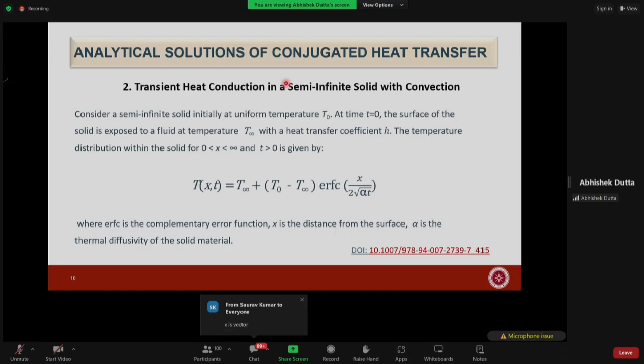These are just some basic parameters to understand the concept of the analytical solution. As you have correctly guessed, a semi-infinite solid is a conceptual solid, which is a single plane surface extending to infinity in all directions except one. If a sudden change happens to this surface, one-dimensional conduction will happen. So it's a very unrealistic reality, by the way. Let's put it like that.